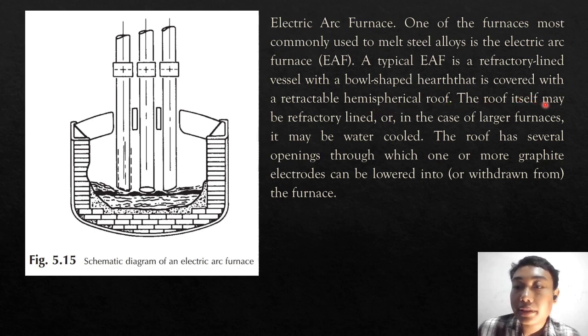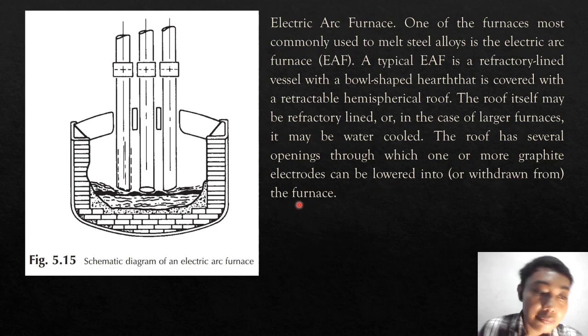The roof may be refractory lined, or in the case of large furnaces, it may be water cooled. The roof has several openings through which one or more graphite electrodes can be lowered into or withdrawn from the furnace. This is the picture of